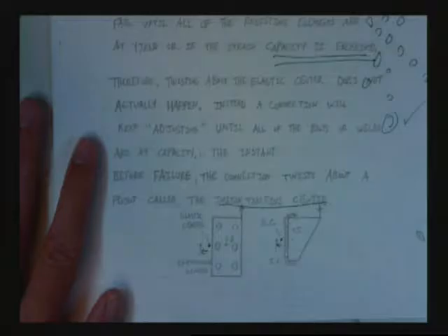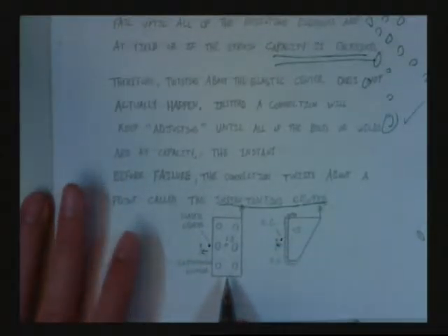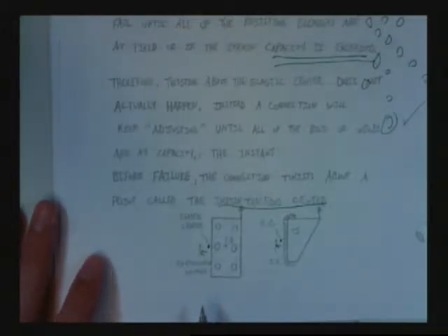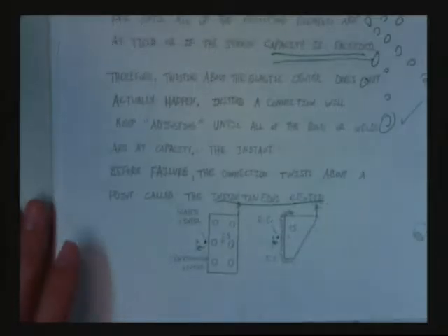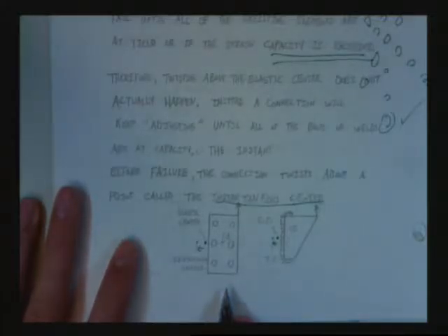Now, if you ever run into some kind of crazy connection, and you want to justify why you want to go with something more standardized, very easily you can calculate the capacity using this elastic analysis and this inelastic analysis, and you can show there's about a 30 to 40% difference in connection material needed. So imagine saving 40% on every single connection in your structure. That is a whole lot of money. And architects, even though they love beautiful things, I do too, usually when you start talking real money, they'll start agreeing with you. Unless their name is Santiago Calatrava, but that's a different story for a different day.